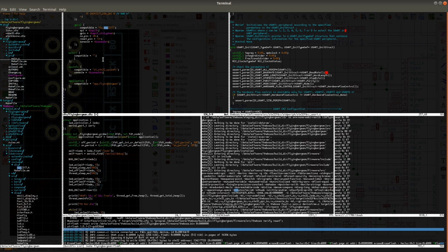However, there can be certain issues with doing that, and the most obvious issue is that this is quite a real-time task to control the motor, so it's likely that it will need to be implemented directly in the interrupts.